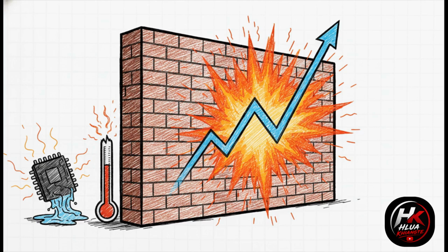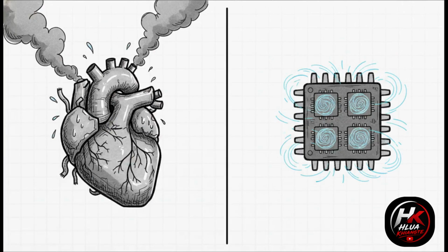If you try to double the frequency to make a faster chip, the power requirement spikes exponentially. And all that excess power, it turns straight into excessive heat. Engineers quickly realized that pushing clock speed straight up would literally melt CPUs right through their motherboards. No way around it.